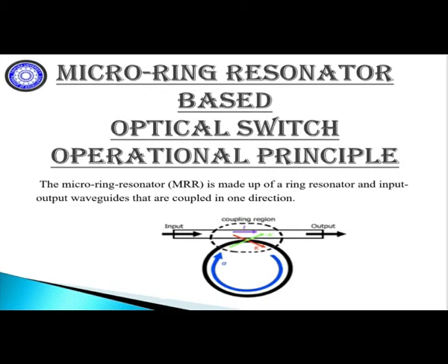The constructive interference occurs when the optical path length of a round trip is a multiple of the effective wavelength, and the MRR is therefore on resonance. Periodic fringes emerge at the output ports as a result. A fraction, K2, the coupling coefficient between the ring and the output waveguide, of the built-up wave inside the ring is coupled to the drop port that exhibits maximum transmission at resonance. The ring has a minimum at resonance in the through port.